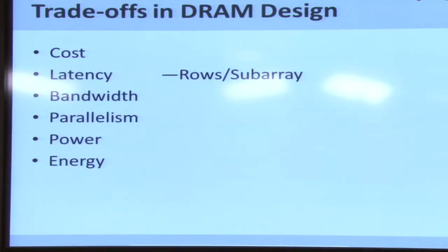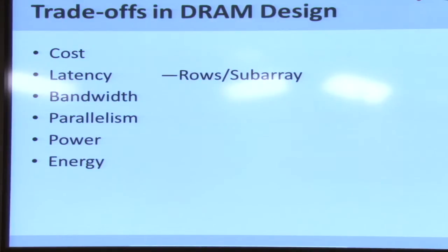Bandwidth. What do you think affects bandwidth? Okay, let me ask a different question. Why do you think I have 8 chips on the DIMM? Why not just have one? With this, you can parallelly access the 8 banks and serialize the output from these banks.